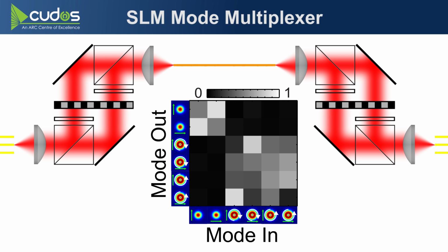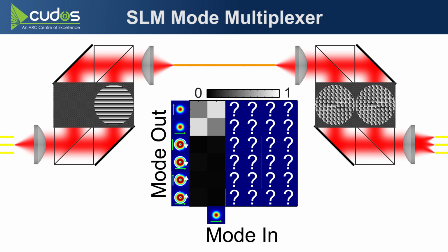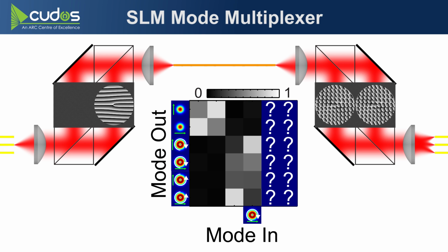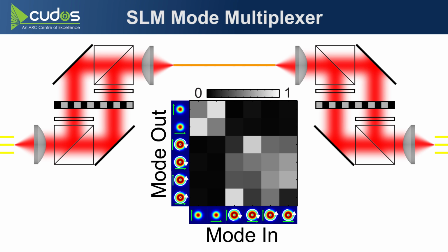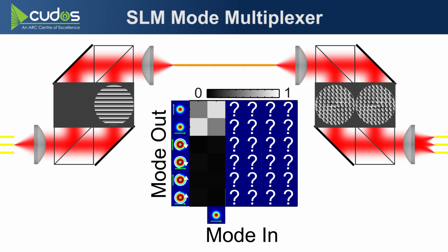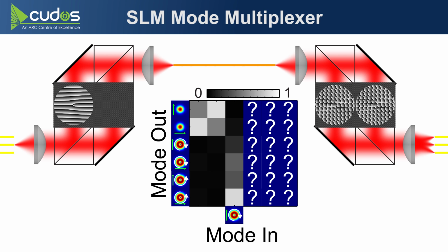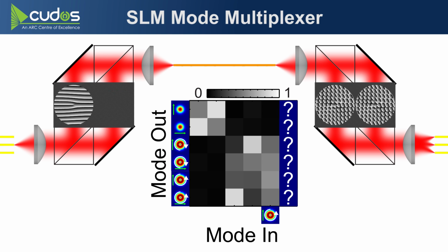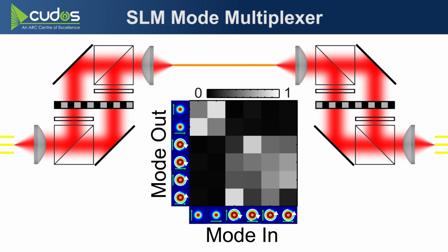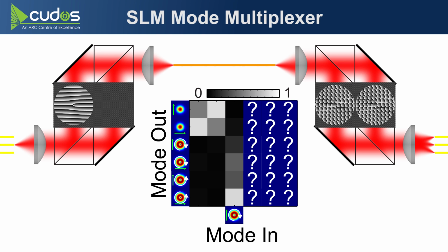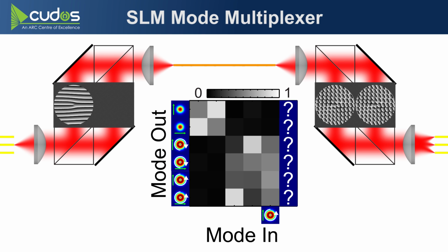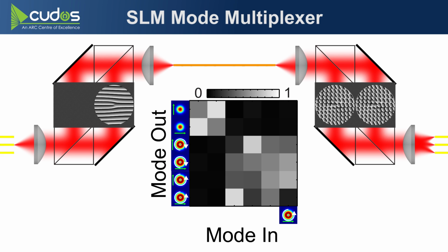This is just a 2-meter piece of few-mode fiber patch cable, and you can see the 2 orthogonally polarized fundamental modes mostly stick together, and the 4 LP11 modes also mostly mixed together. However, that's only partial information about the propagation matrix. If you're also interested in the phase, that's something the SLM can also measure.